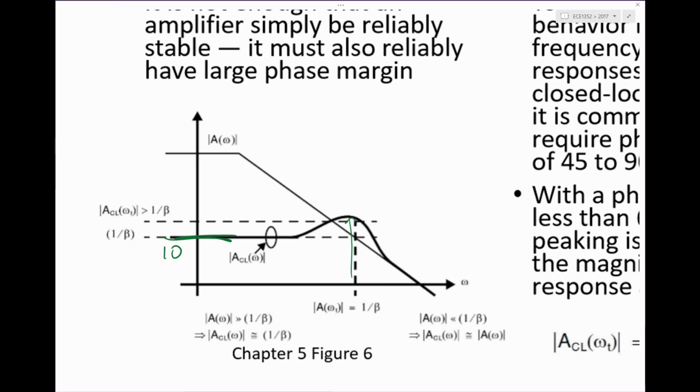And now we know that in order to avoid that, you need a phase margin of at least 45 degrees, right? It means that even if you have a phase margin of 40 degrees, you can't just think, oh, I still got tons of margin. No, you're already causing a problem in the system. Something might break because of that.